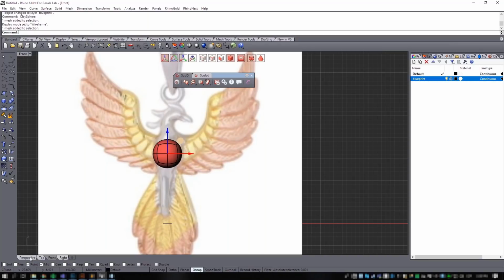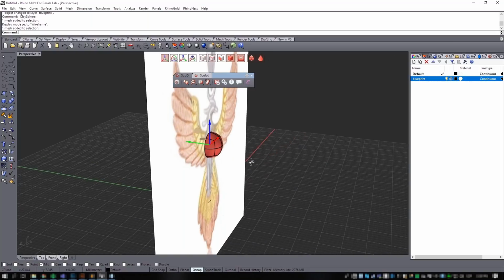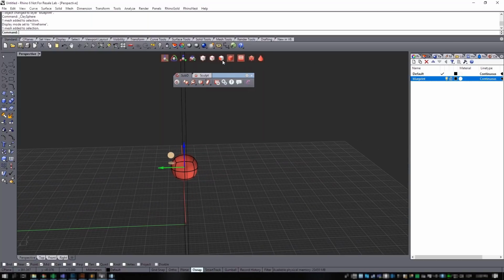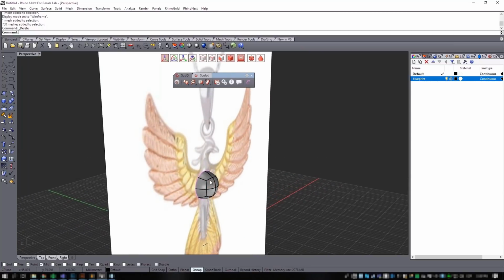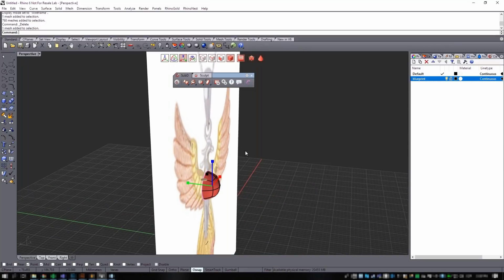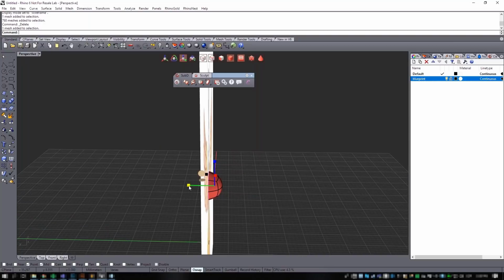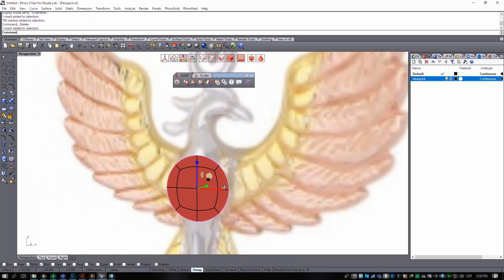Right now what I'm going to do is make sure that this sphere is in a single plane. So from here, I'm going to select a few faces from this sphere. I will select half of the sphere, and I will delete this part of the object. Now, I will select the entire object that I have, this half of sphere. With the scale gizmo, I double click on the green axis and I click 0 just to scale it to 0. So just to make this object perfectly plane.